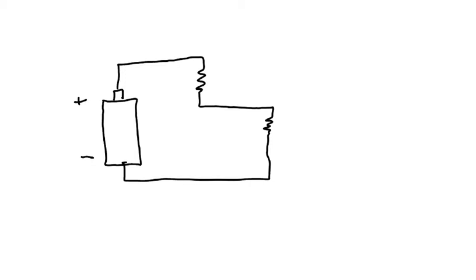Now just a note about current. We define current as the flow of positive charges. They leave the positive end of the battery and then travel through the circuit in this direction. We know that the positive charges are the protons, which are pretty well fixed in place. And so it's actually a movement of negative charges, of electrons, that's taking place here. So this idea of positive charges is really incorrect physically, but we didn't know that for a long time when we were describing electricity. So we call that conventional current.